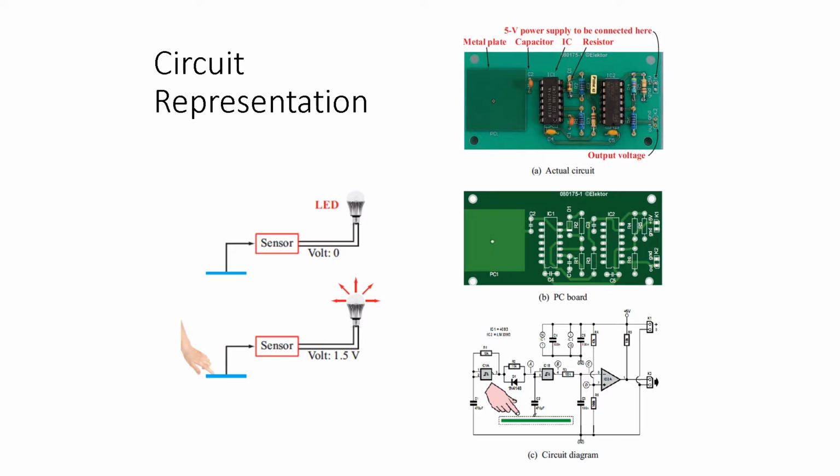So the next bit that we have is the PC board, and this is solidly in the realm of mechanical engineering. The PC board contains essentially all of the wires that connect the different components together. So those individual components, like the capacitor, the resistor, the ICs, all have to sit and connect in a proper way. Now, you could do that with a breadboard and kind of hook them up, or you can solder individual wires. They call that, what is the name for that? I think it's bugging. Like you have a little circuit bug, where all the individual pieces are wired together. It's very messy and it's not very reliable, and you have to do it by hand.